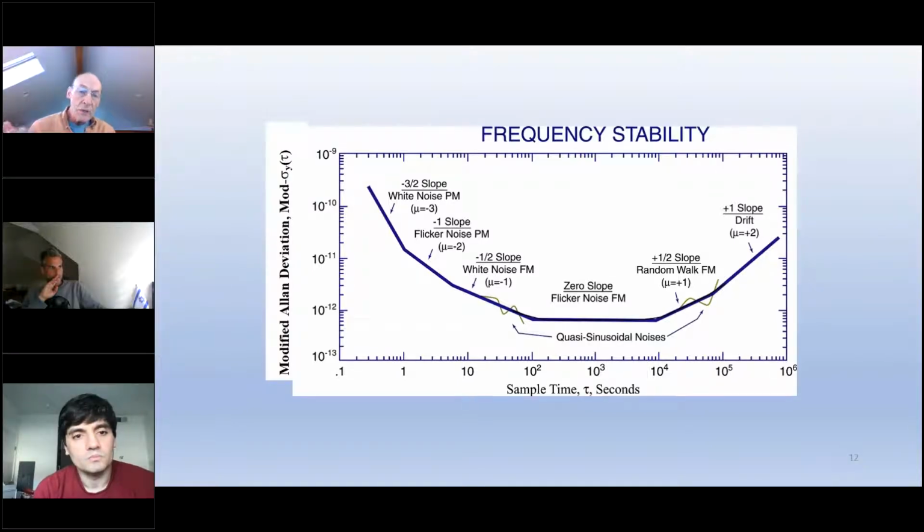And if it's white noise and you compute the modified Allan deviation and plot it on this log-log plot, it goes down as -3/2. If it's a random walk in phase, but white noise in frequency, it's the same as white noise in frequency. Now it goes as -1/2 on this log-log plot. And a little confusion, because the variance is the square of the deviation.